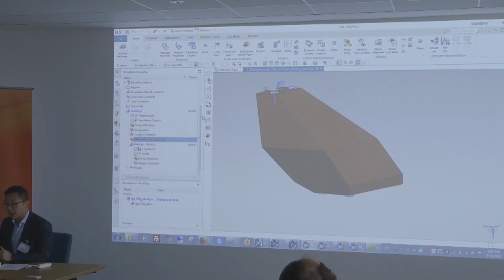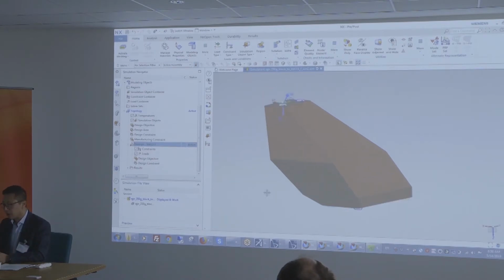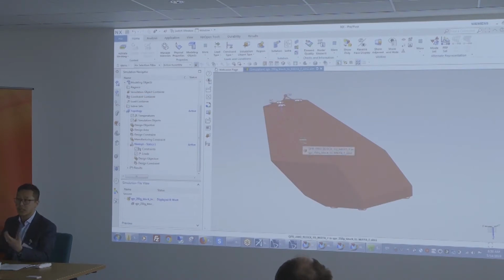But before I go ahead and define those, what am I going to study on this bracket? What kind of geometry will I want to have? Well, I'm going to be exciting this geometry and subjecting it to 100 G loads in X. In the space application, because of takeoff, we'll want to have a minimum natural frequency. So I'll try to add that as a constraint as well.